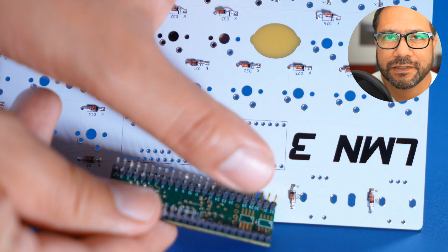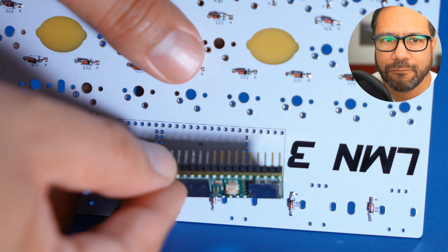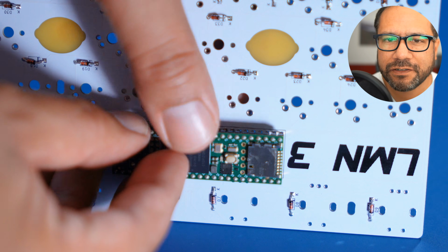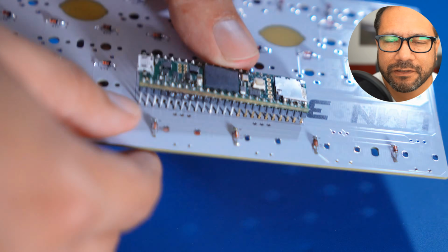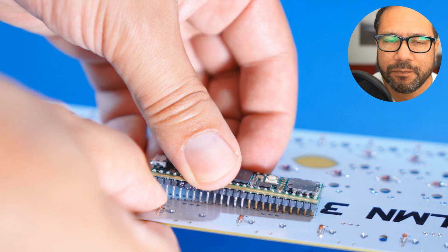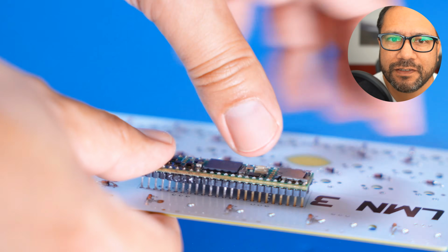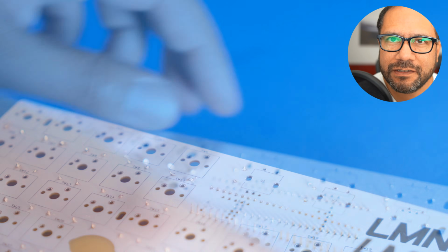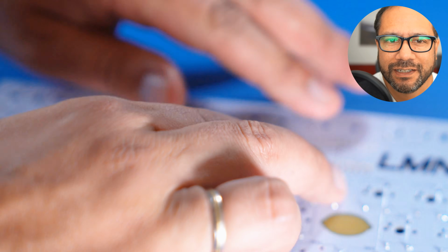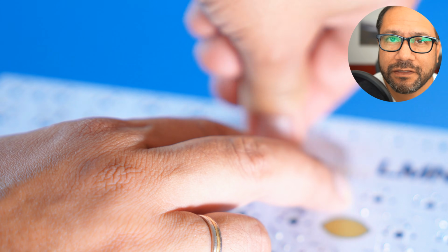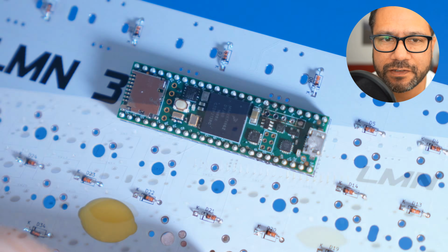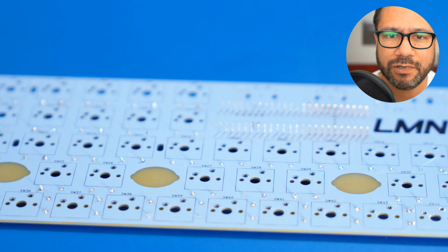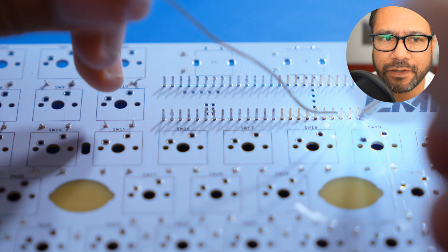Turn the board around so you can see the diodes, then take a look at the way the holes are aligned on the PCB. The Teensy has the same pattern on its body, so align it accordingly. And then carefully push the pins through the PCB. This might take some tries and readjustments, especially if you used the Teensy in other projects previously. It's a good idea to lay the board and the Teensy on its back once all the legs are through, and gently but firmly push the PCB until the Teensy is in place. Then solder all the legs.